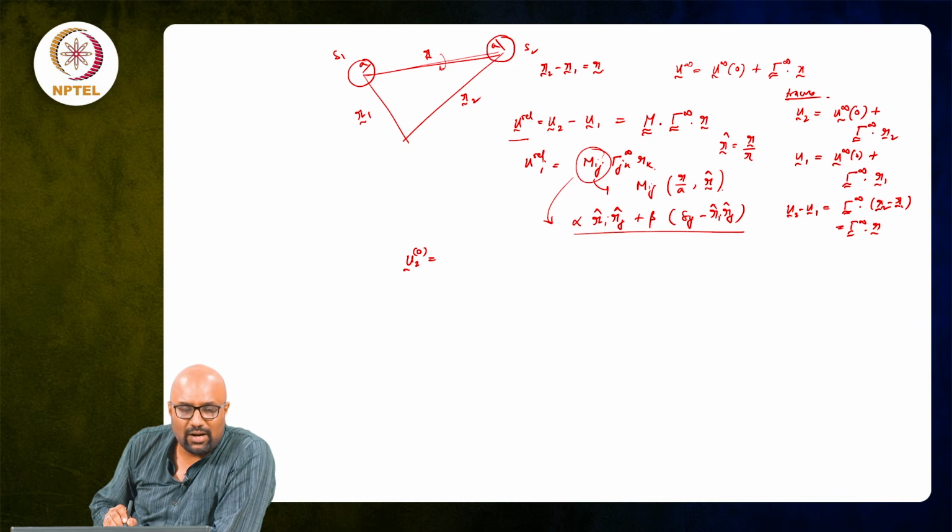So, in a background linear flow, a sphere which is force free and torque free should spin with the background vorticity, or half of that vorticity, and will move with the fluid velocity at its center, right.